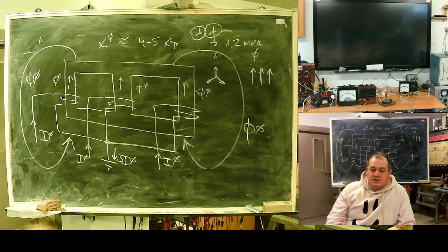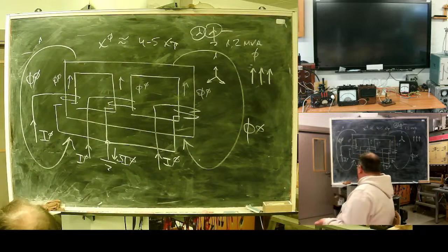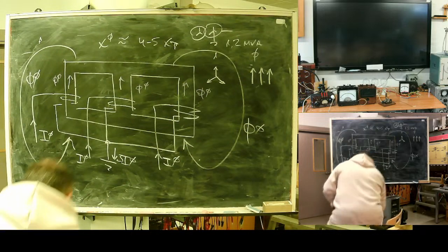Zero sequence current can flow to the transformer, but zero sequence magnetic flux will close in the transformer vessel, causing heating, possible overheating, possible fire. Yes. Another kind of transformer.